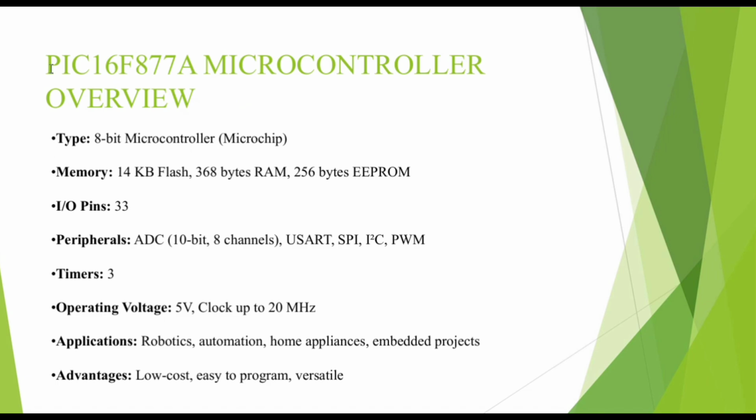Let's see this PIC16F877A microcontroller overview. This is an 8-bit microcontroller. It has a memory of 14 KB flash, 368 byte RAM and 256 byte EEPROM. Then it has 33 input output pins. Talking about its peripherals, it has an ADC 10-bit 8 channel. Then it has 3 timers. In the operating voltage, it has 5 volt and clock up to 20 megahertz.